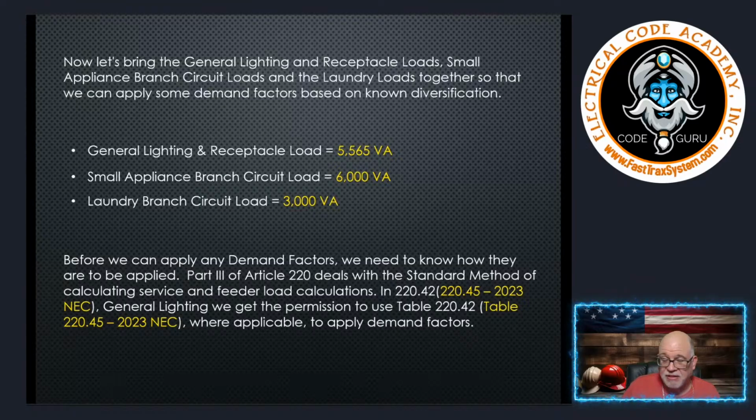Okay? Got to have at least one. Now, whether you use it or not, it's totally up to you. But you have to have the laundry circuit in using the standard method for that calculation. Okay? All right? Because the code tells me I do.